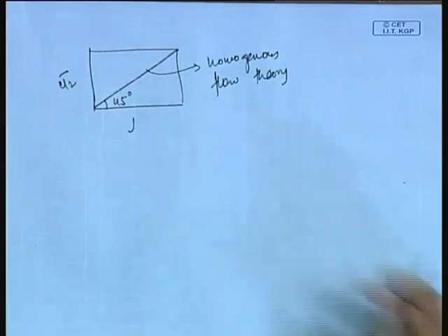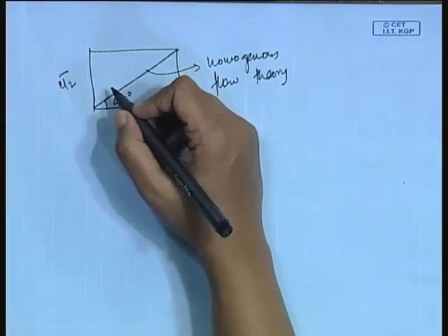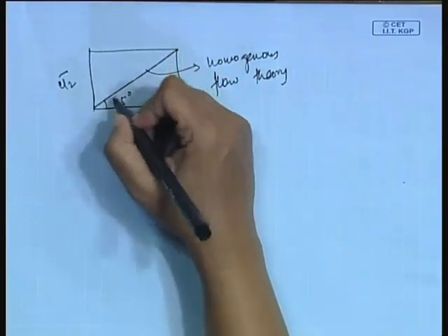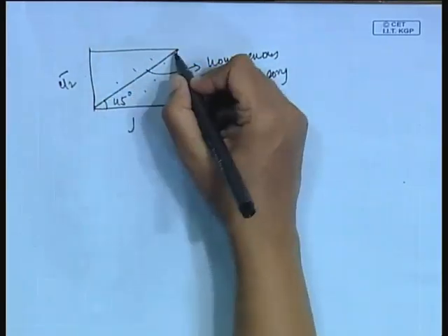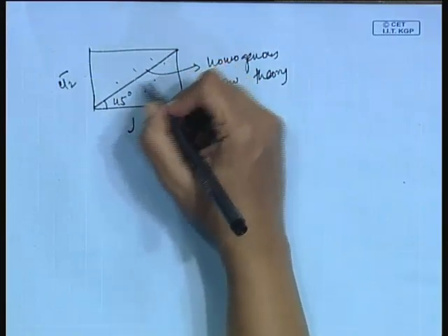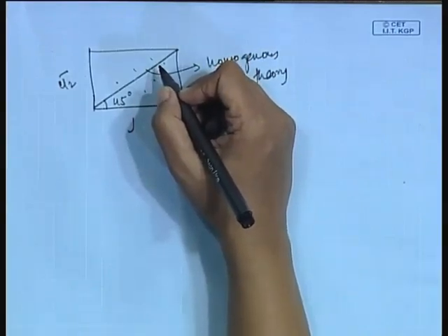Now, whenever we get experimental data, we try to plot it on this particular curve with the 45 degrees line on it. Okay. And then we see the spread of the data. From the spread of the data, we try to understand how much it has deviated from the homogeneous flow theory. Accordingly, we introduce corrections.